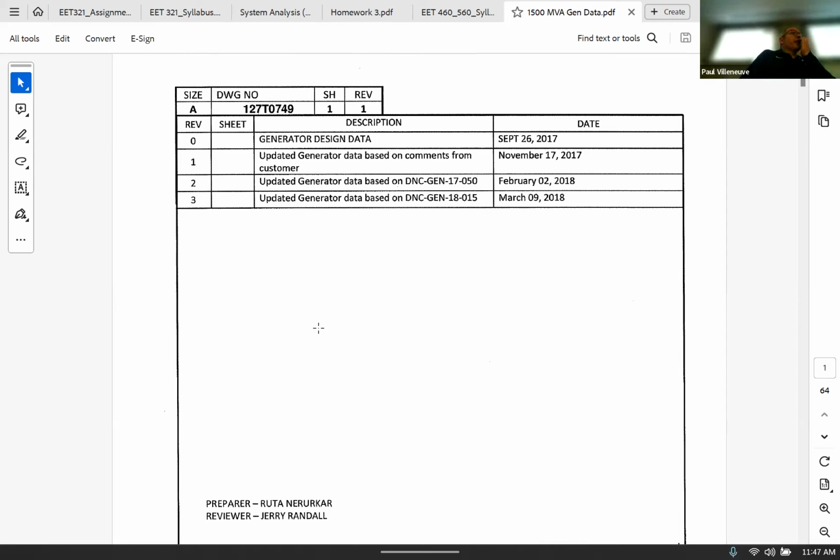A 500 MVA transformer is a massive transformer. You're probably going to have to ship that over rail and then rent a special truck to get it onto your facility. So in that case, you actually would buy 3 single-phase transformers, because a 100 MVA transformer would be almost as big as a quarter of this building that we're in. You just couldn't ship it. So you would buy single-phase ones, and then you would just patch them in together there.